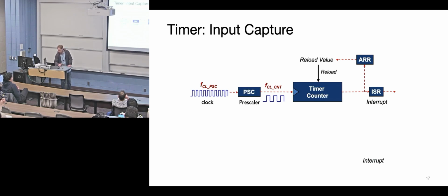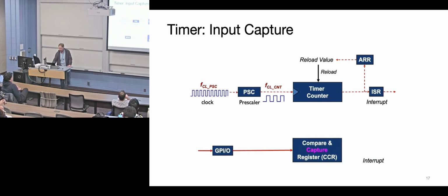We have a capture timer here. So here we're in capture mode. So then you have some timer that goes off. When the timer goes off for whatever reason, you can produce an interrupt service routine. That's one of those wires that goes back to the NVIC. You have the option, if configured correctly, to have an auto reload register, which says when it gets to 0, start counting back up to some value. Or, if you're decrementing and you get to 0, then it reloads that value in there. So basically it's either the alarm when it goes off or your starting point when you're counting down, okay?